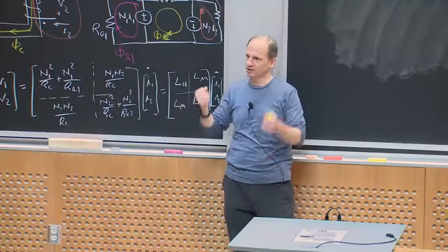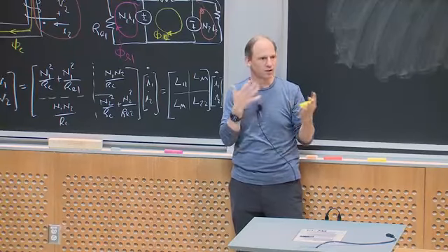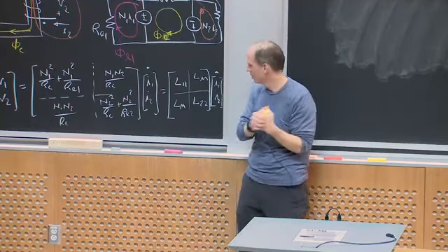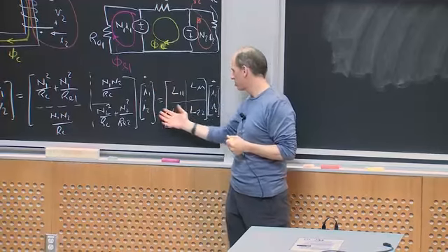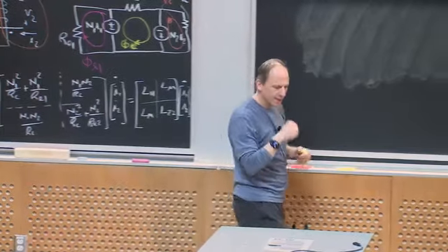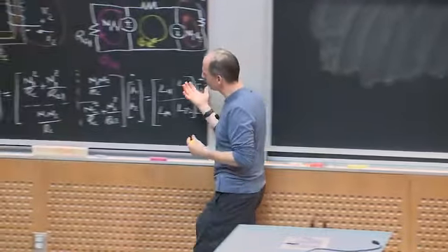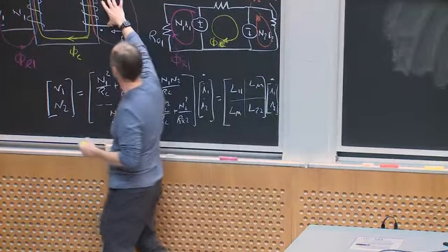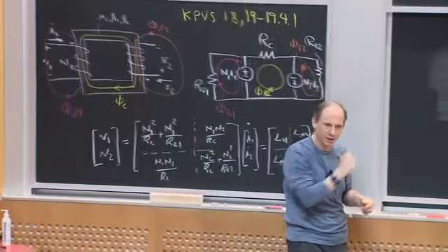So if you have an inductance, that's kind of one parameter that models everything. If you have a 2-port structure, 2 inputs, 2 outputs, or 2 different terminal pairs, then you get a 2x2 matrix, okay? And the matrix turns out to be symmetric, as you can see. We derived this in class, okay? And then we took this one step further, and we kind of went quickly, but we said, okay, this inductance matrix describes the terminal relations I get ideally between this voltage and this voltage and current, and this voltage and current, okay?